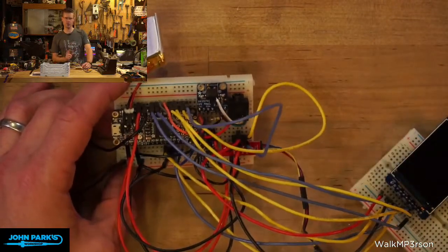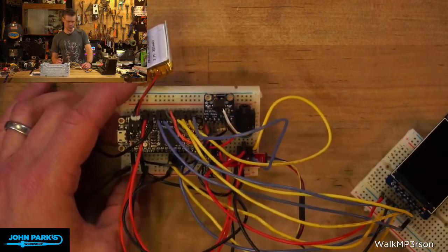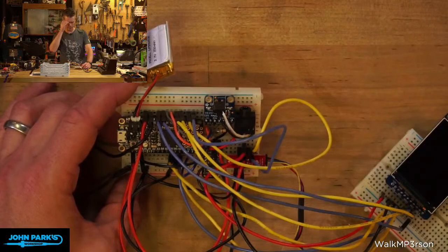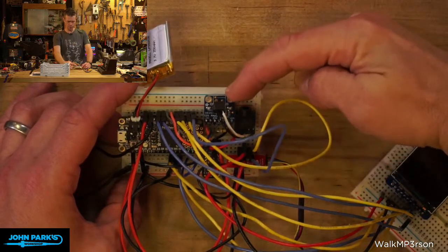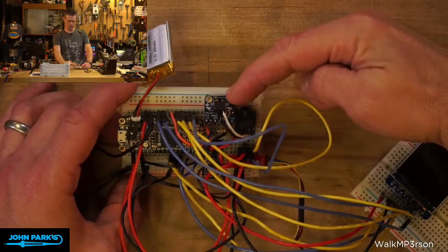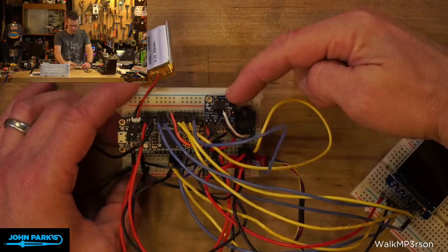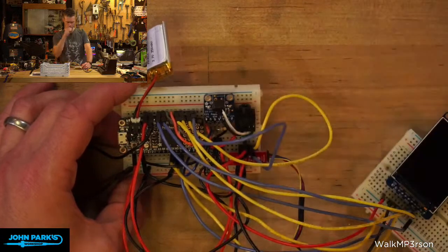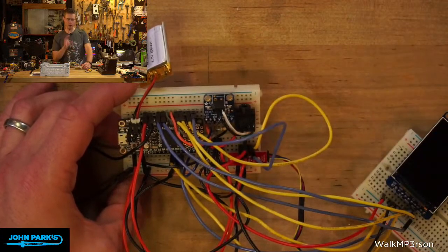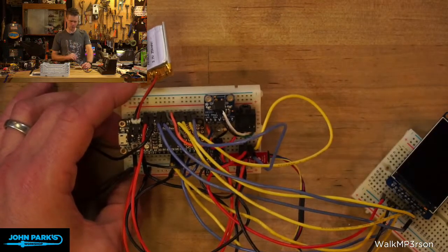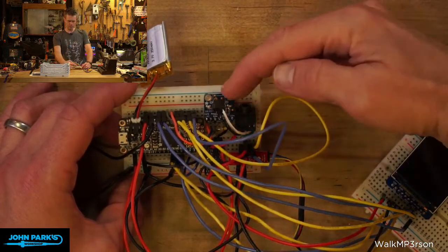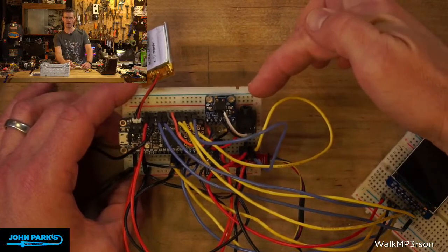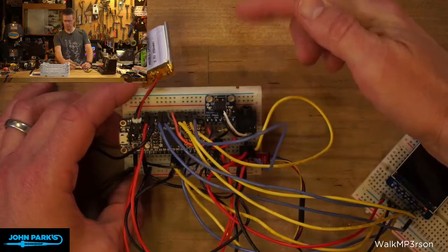So the other thing I found out is that this amp really wants 5 volts. I'm not sure exactly why, and Lady Ada is looking into this because it's actually rated for 2.5 to 6 volts or something like that input voltage on this little MAX98357A chip, which is this one here. For some reason, it's really noisy when I have 3 volts, no matter the 3-volt source. I've tried a bunch of them. When I give it 5 volts, super clean, really clean sound, kind of the cleanest sound I've gotten off of a microcontroller with an amp.